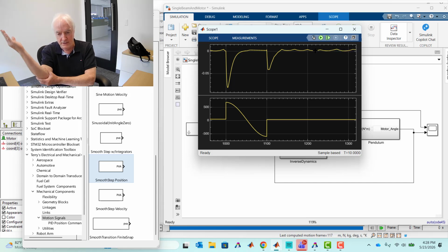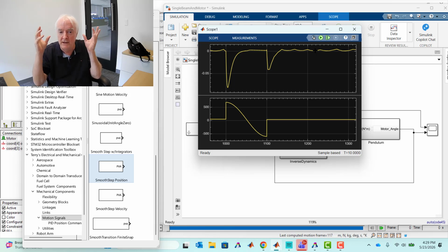As we bring that beam up to 45 degrees, and even as we hold 45 degrees, there is a tendency to drift. Because we have an immediate measurement that's being fed back immediately, the PID has the ability to rapidly address that drift and restore it to the angle that we wanted. So that's the basic idea, and why PIDs are so good. There are lots of things to talk about with PIDs, but certainly that's an aspect of it that really helps us keep this thing stable.